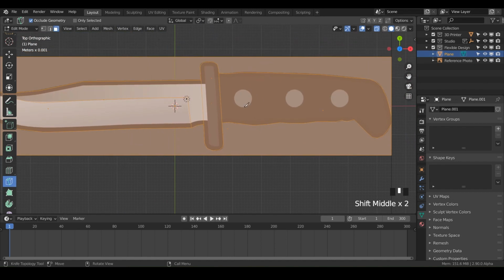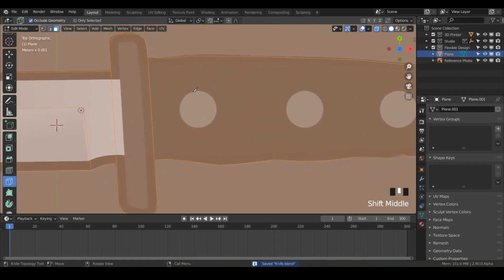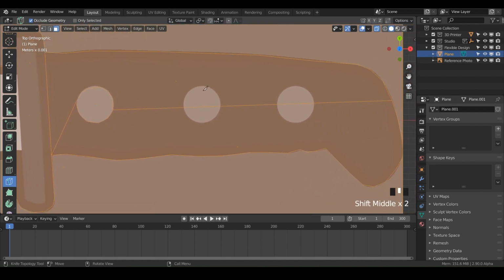And while we're at it, let's go ahead and get these little circles. I'm going to do this real rough. And then hit enter. And notice it cut out the geometry for us. It made some new lines. That's just Blender trying to help us out and making the mesh work. So it needed to connect to something, and so it just made it do it. And you can see as I get closer to that line, it kind of magnetizes to that.